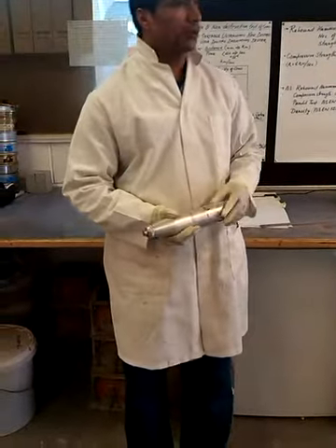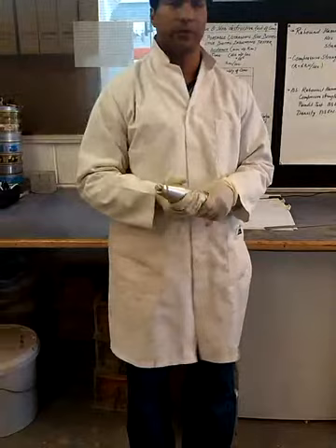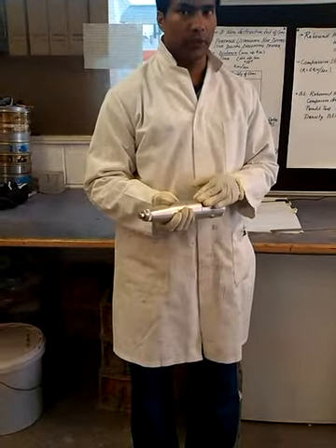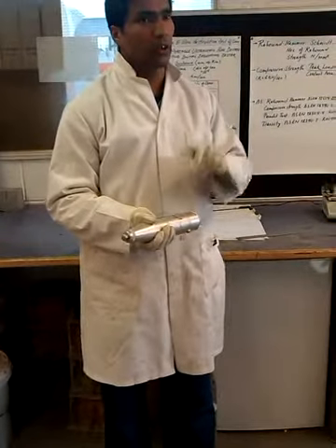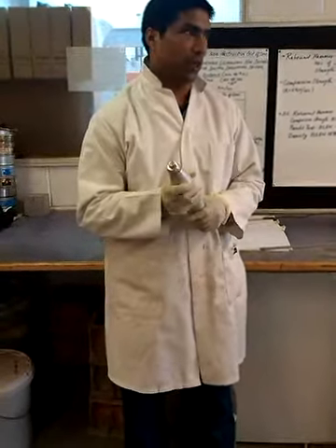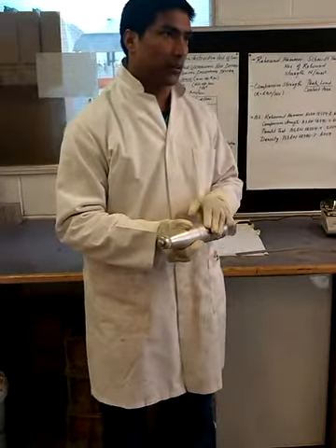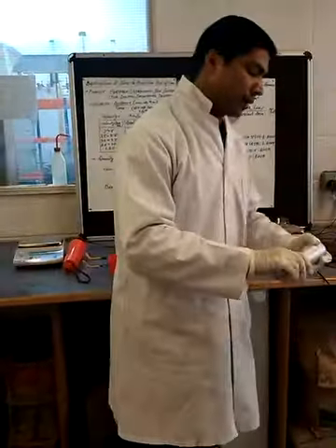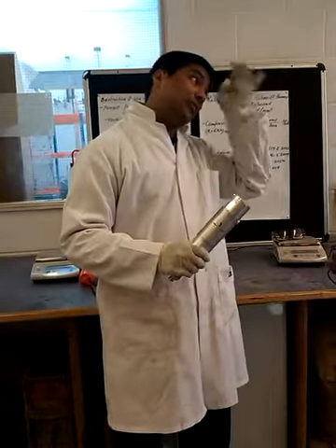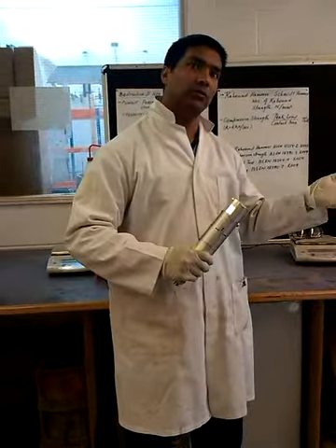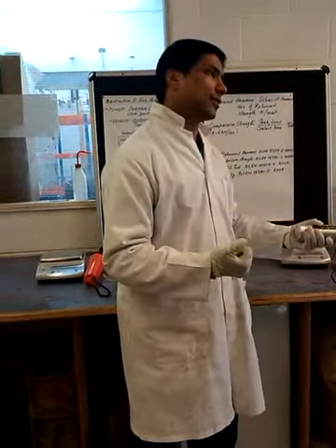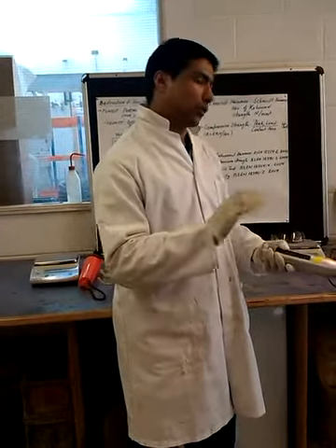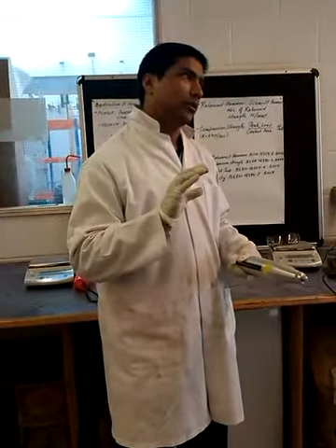Only thing is that to compare the strength of the concrete using this hammer and using that compression testing machine, this hammer needs to be calibrated. Without calibration, the strength that you are converting from this one may not be equal to that from the strength machine. So it needs to be calibrated because in the market you will get different types of hammers with different energy, and accordingly you use them for the concretes. And you need to calibrate from the starting of the concrete casting, so that you can get the equal type of strength.